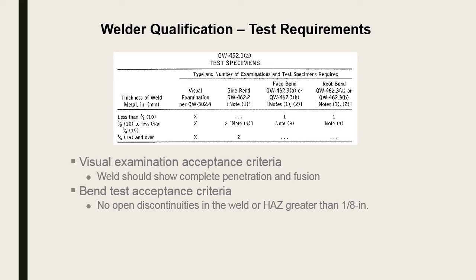That's general for most weld codes. There's going to be some subtle differences. ASME Section 9 and AWS D1.1 have a couple of subtle differences on the acceptance criteria and how they're measured in regards to openings, when something opens up. But that's the general gist of it: with most of these codes, you're going to do a bend test, and then you're going to look and make sure there's no openings or a crack or some kind of discontinuity that would be cause for rejection.